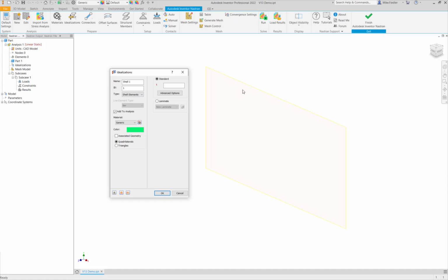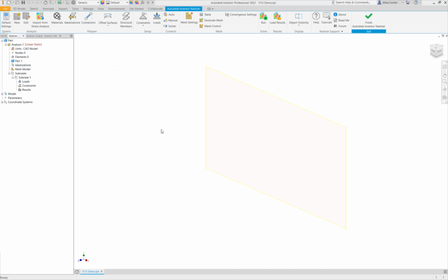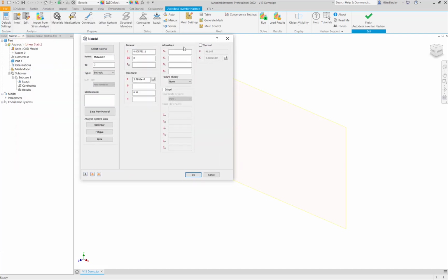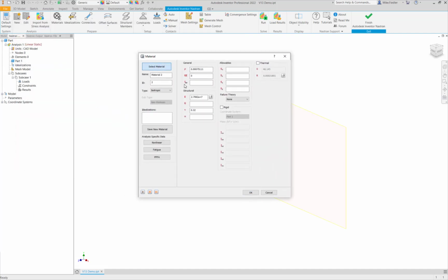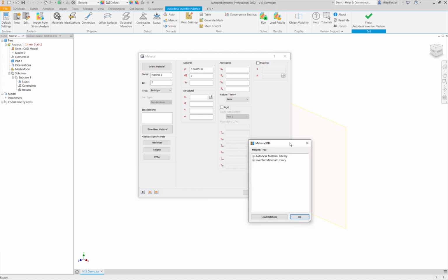And because I have a planar region, right? Remember the whole model is a 20-inch by 10-inch. I did a 10 by 5 again for the quarter symmetry, but we don't have any thickness modeled. So we do need to tell it what is the mathematical thickness of this plate? And that was defined for us in the problem as 0.1 inch. And then for the material, let's go ahead and select that button so that we can access the material. We could do something like select material.